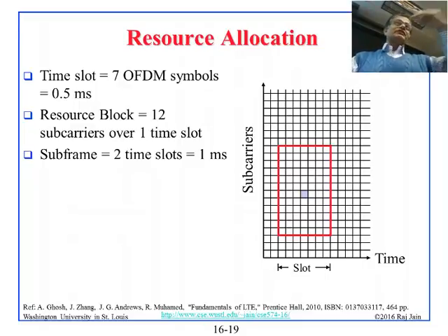All right, the map actually only comes in the downlink direction. In the downlink frame, there is a downlink map that says if you get this whole frame, this is your bit, this is your bit. But it also says that in the next uplink, here is the map. So the uplink map is in the downlink. It says that when the next frame comes in, you can transmit at this frequency at this time, you can transmit at this frequency at this time. And this changes every frame.